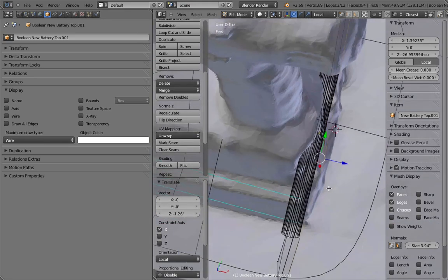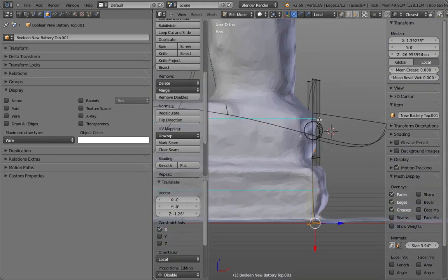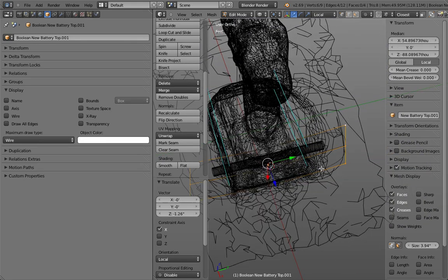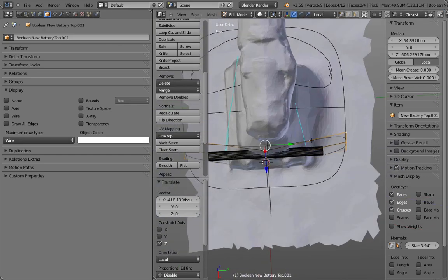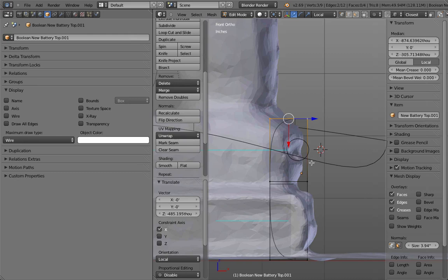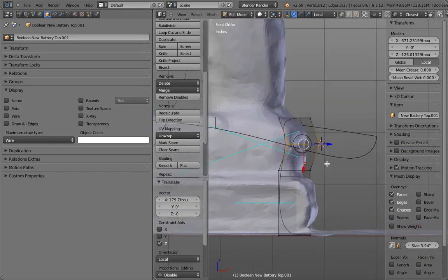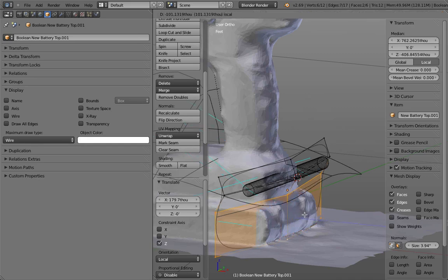So I know on one side it arcs this way, and from a side it arcs this way. So selecting those side points, I can, for example, define this arc. And then I have to define also this arc. So maybe for the moment I put this one down, make a loop cut, move this one forward, and maybe Alt click on those edges, move those inwards.